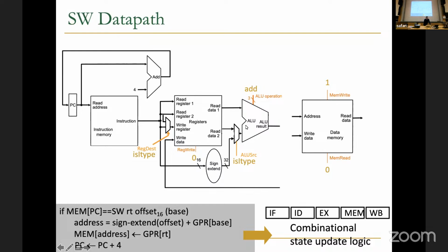Yeah, exactly. And then add it to its sign extended 16-bit offset. That's good. That's our address calculation. Now the ALU result is the calculated address. That needs to be connected to the address. That's good. Now what should we do to this port? Now that needs to come from the register file. That's good. So you can see that we're actually making use of what comes out of the register file second port over here, as specified by the store word instruction.